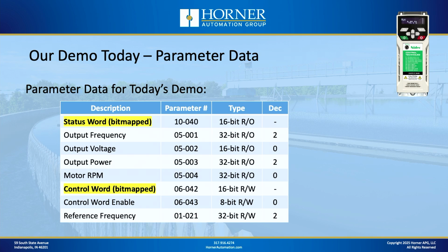What's the frequency of the drive, the voltage, the power, the RPM. Those are just examples showing you how to monitor that sort of data with read-only information. And then on the output side of things, in addition to my control word, I've got a bit that I've got to turn on to enable the control word. And then I'm going to be controlling the frequency of the motor, of the drive effectively, through an additional read-write parameter. So that's what we're going to be working with during today's demo.